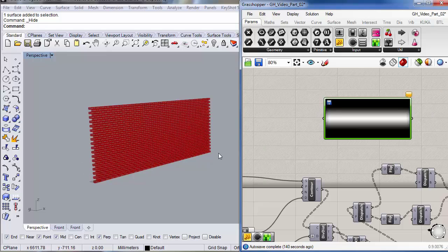I always thought that I was sampling here, but what happens here is it's using X and Y values, so like say 0 to 1, whatever. So it'll map the points on here as if you were mapping it. I like to picture it like I'm mapping it on the wall. But any Z values, this image sampler ignores. It only uses X and Y values. So I was using points that had an X and Z value but had no Y value. So in essence, I was just sampling a single line along the bottom here and getting very mixed results. And it took me an entire day to figure that out.